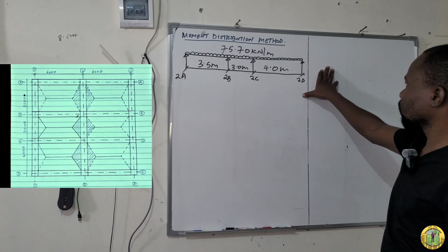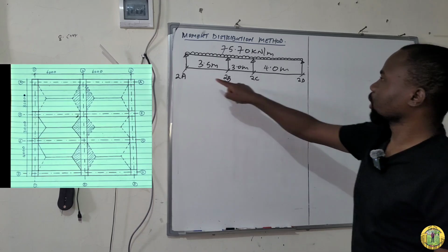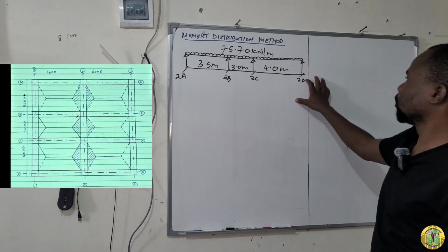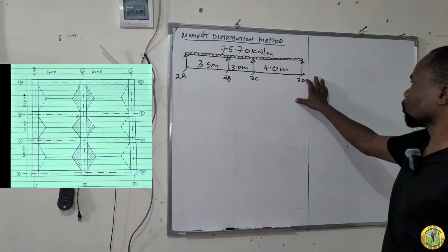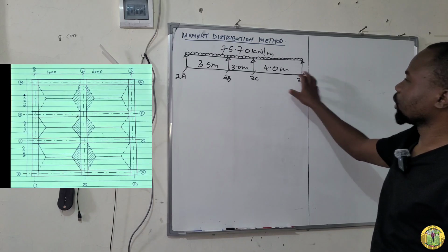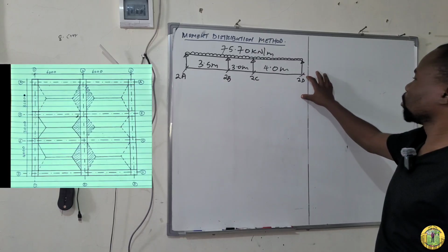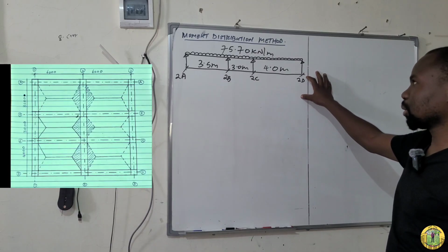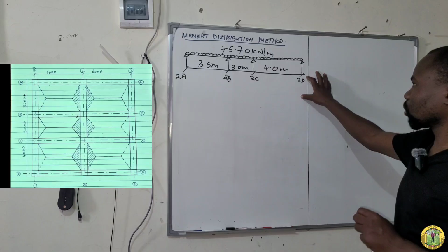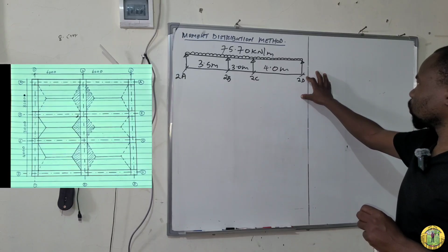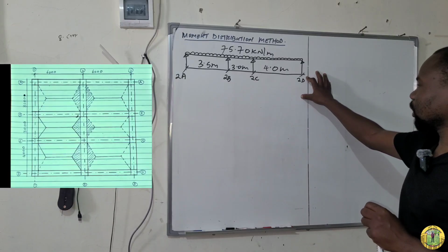Very important things to note on this beam. As you can see, the end supports are simple, so we will assume our end support is a simple connection. But for the purpose of construction, when doing the analysis before design, you are supposed to analyze using 2 different end conditions.